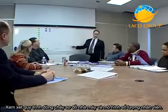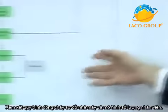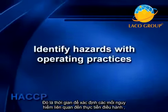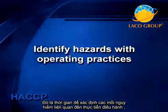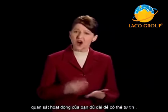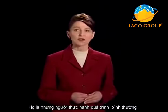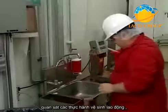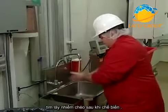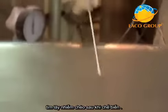Review your process flow diagram, plant schematic, and employee traffic patterns. After identifying ingredient and process hazards, it's time to identify hazards associated with operating practices. Observe your operations long enough to be confident they are the usual process or practice. Observe the hygienic practices of employees. Look for cross-contamination after processing.